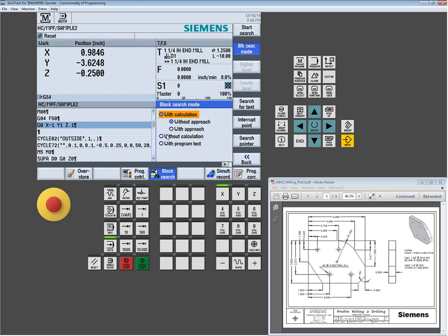If you got a really long program, you're starting from a safe point anyway. Sometimes it pays to just do without calculations. That would be what we would consider a dumb start. So you better make sure that your work coordinates are loaded, all your tool offsets, spindle, that's all there without calculations. So you do with, it's going to scan to the point.